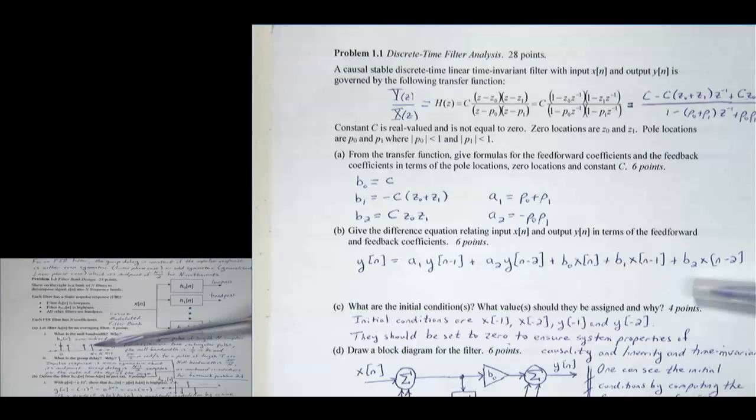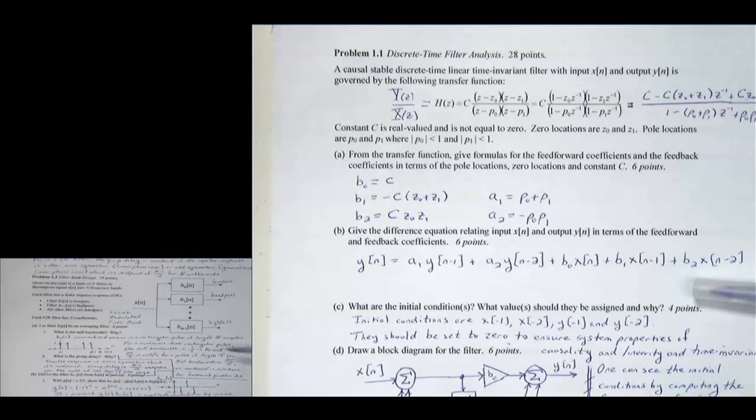Well, first of all, here's the averaging filter impulse response. It's a rectangular pulse. And going back to homework 0, my favorite homework set, you looked at rectangular pulses. The null bandwidth for a rectangular pulse in the continuous time case is 1 over the length of the rectangular pulse, because the Fourier transform of the rectangular pulse is a sinc, and that first 0 crossing is at 1 over the rectangular pulse length in hertz. In radians per second, it's 2 pi over the rectangular pulse length. So you could infer that the null bandwidth would be 1 over n, or in radians per sample, 2 pi over n.